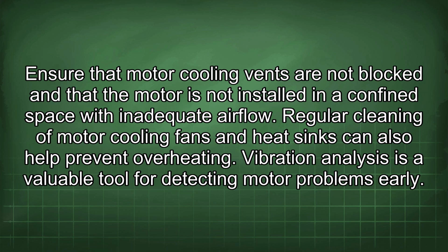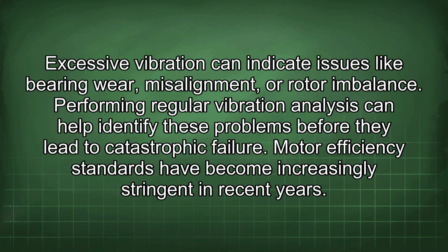Vibration analysis is a valuable tool for detecting motor problems early. Excessive vibration can indicate issues like bearing wear, misalignment, or rotor imbalance. Performing regular vibration analysis can help identify these problems before they lead to catastrophic failure.